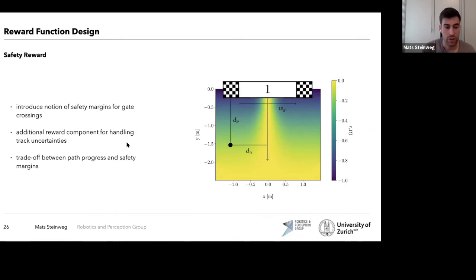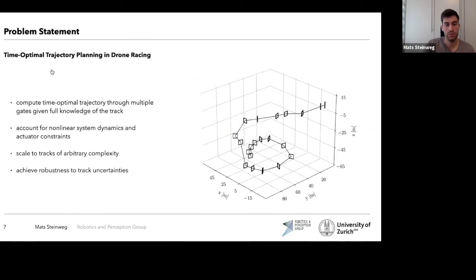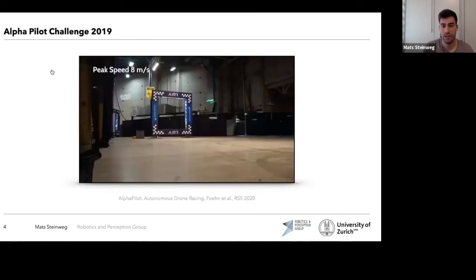Yeah, so I think here we have to differentiate between the actual real world quadrotors that we saw in the beginning. So here, if we jump to this slide, oh no, sorry, here it is. Here the maximum speed that was achieved is actually 8 meters per second. And the main limiting factor here is actually the state estimation part, because if you go for higher speeds, you get a substantial drift and a larger error in the estimation of the state. So you get inaccuracies in the information about where your drone is, and this makes it very complicated or impossible to control your drone anymore.